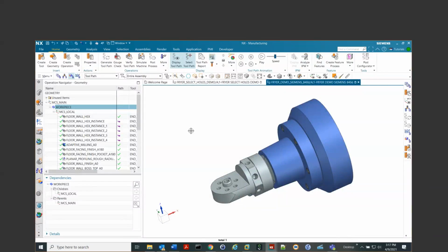Now, what's interesting is when you get to a lathe, it's not like that. Instead of spinning the tool around the part on a lathe, we let the part spin. I think we chose this method in a mill because we never know what kinematic type we could have. Maybe I have a head, so my rotaries are up top and my tool is actually moving. Or in this case, I have a rotary on the table, then the part's physically moving. So it was probably the most universal method, but great question.